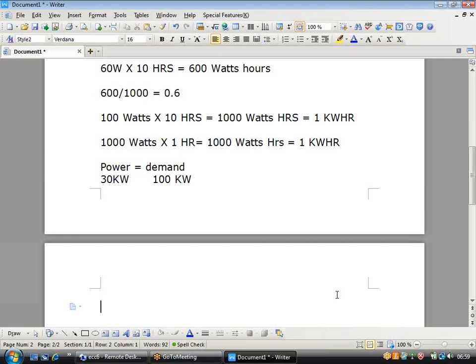It is for each billing period. Suppose my billing period is 1 month. For every month there may be several instantaneous starts of the equipment. Maybe on the first day when I started, instantaneous power was 20 kW. Second day I started, 25. Third day or fifth day when I started some machines, some machines may not run all the time. Some machines may run only during a particular production schedule. So what is the maximum power it demanded at one time for 15 minutes in the month?